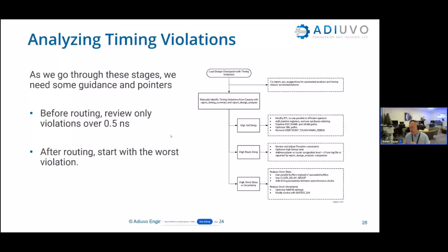We might want to not just use all the outputs of the MMCM. We might want to take an output from the MMCM and then divide it using a BUFGCE divider, for example, to remove some of the phase error that can contribute to the clock uncertainty in there.